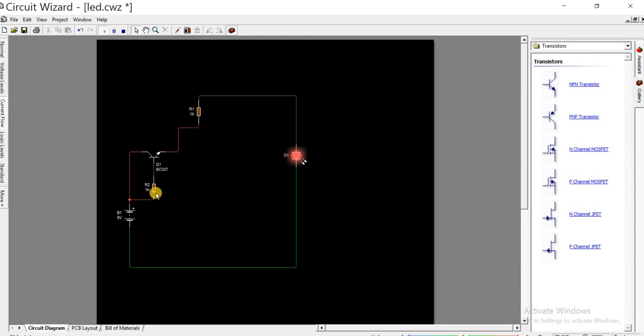So we are connecting it like this because we are using NPN. Okay. So try to connect it with a PNP transistor, and let's see how it looks, and simulate it by yourself. Okay, so now let's use this circuit. Let's use a voltage divider with this circuit to make it more meaningful.